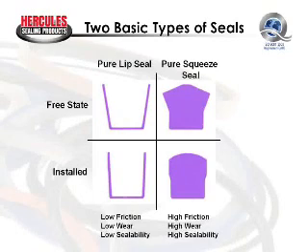What would be true at high pressure? Which seal is going to seal more effectively, the lip seal or the squeeze seal? Well, it's a trick question because at high pressure, if you remember, we said the shape of the seal has very little to do with sealability. At high pressure, both of these seals are going to seal adequately as long as they don't extrude. So assuming there's no extrusion, both seals will seal effectively at high pressure. It's only at low pressure, when we have most of our sealing problems, that you need to worry about a choice between a pure squeeze seal and a pure lip seal.